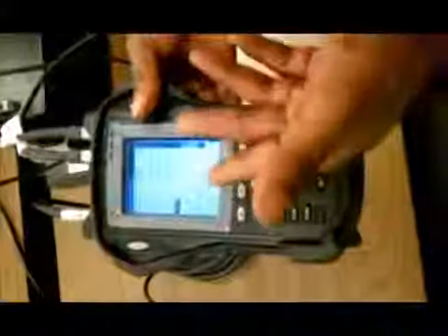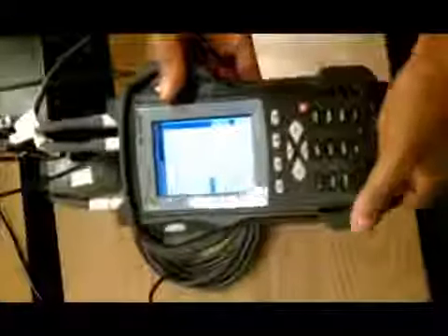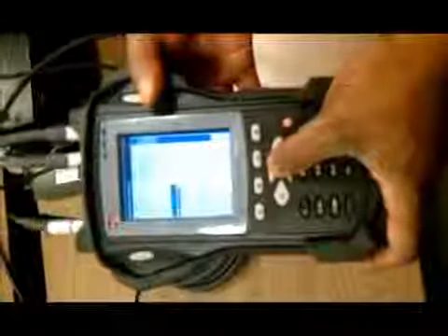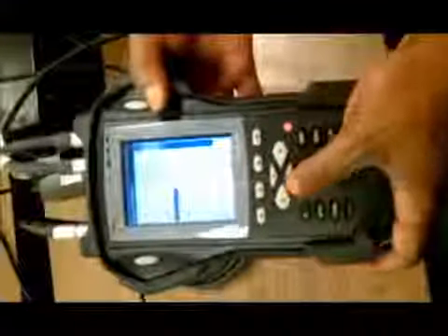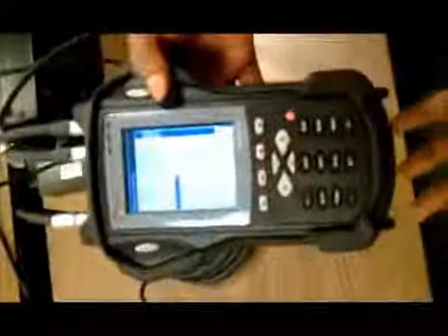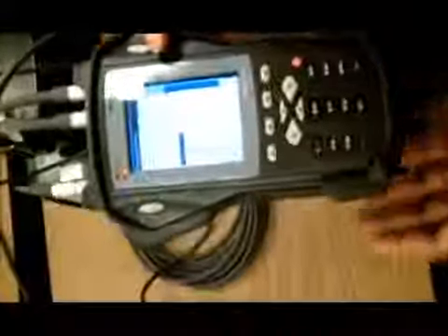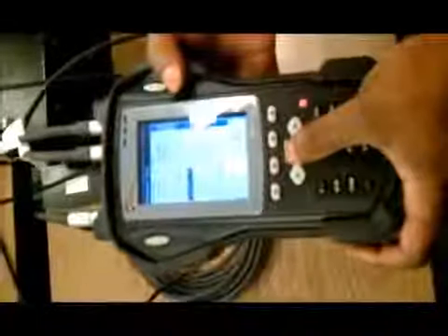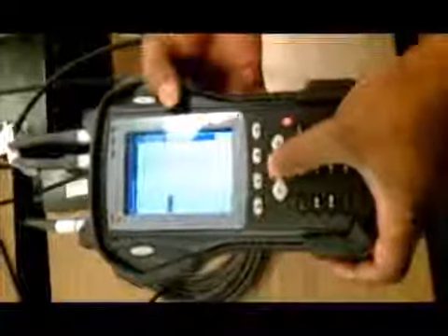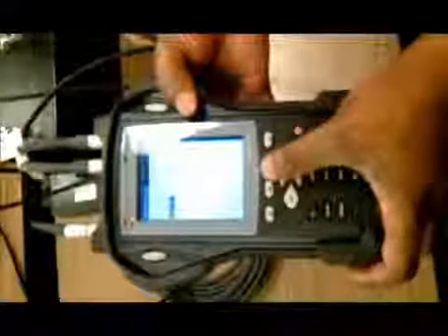And we have our type, which is whether it's continuous, meaning we can put weight anywhere around, or if it's fixed, where we have fixed positions to put weight. So in this instance, we'll have continuous, and we'll set the second plane the same way as we set the first plane, except we'll have channel 2 for our second plane. If we did have an issue where one side was continuous and the other side was fixed, we can set up each plane independent of the other. So we'll hit apply, and we're ready to start.